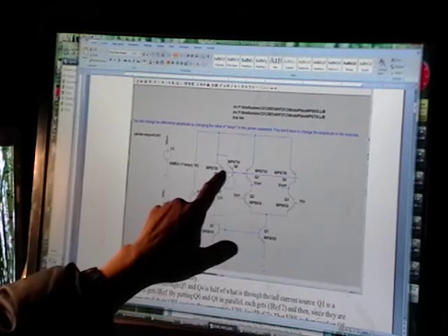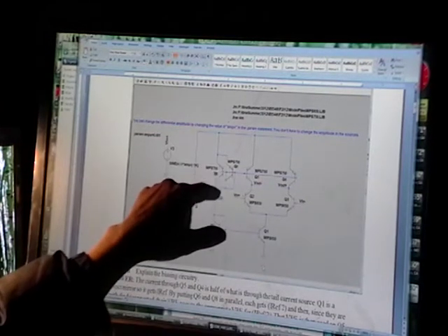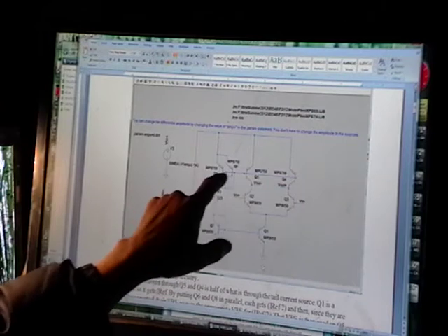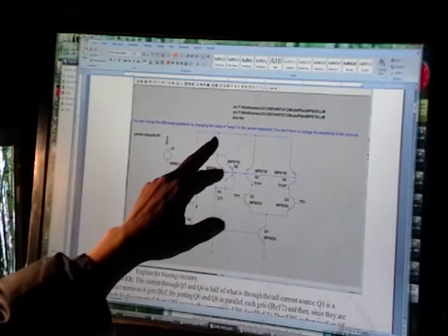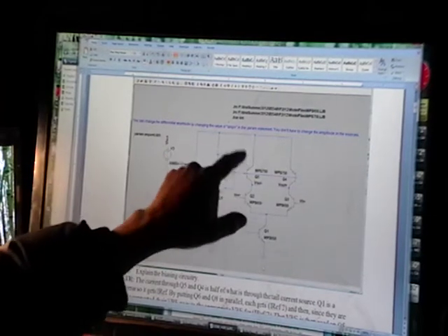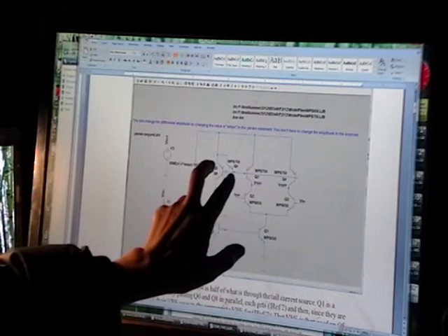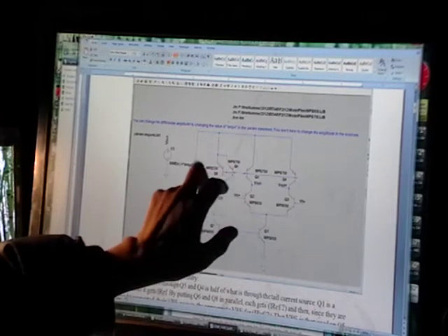By putting two transistors in parallel, you get half of the current going through each of these. And since only half the current's going through each of these, set a VBE for only half the current. And now when you use that over there, now you're setting for ISS over 2. So if this is ISS, then you have ISS over 2 going through each of these. Each of these set their own VBE to conduct ISS over 2, and that's what you want in these guys. So that's the first question.